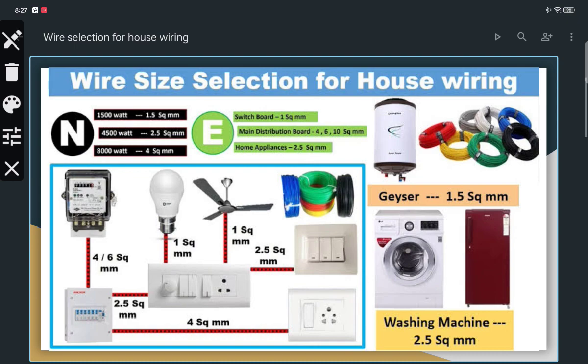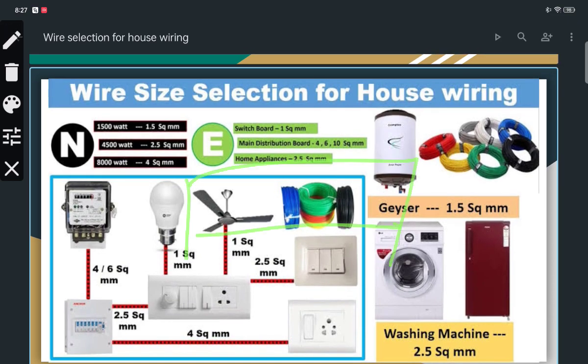First, you will see from 1 square mm; it has a list like 1 square mm, 1.5 square mm, 2.5 square mm. There is no 2 square mm wire in the market. So 2.5, then 4, then 6. There is no 3 square mm. If you go to a shop and ask for 3 square mm, there is no such size of wire. Okay, so 1, 1.5, 2.5, 4, 6, and that is what the standard is. And then 6 square mm, then 8 square mm, then core.